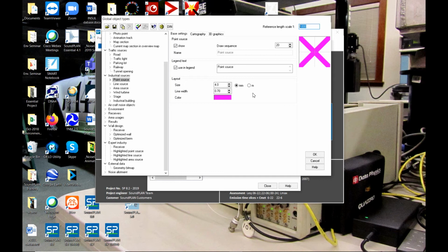What is your reference scale? So if you typically work on projects that have larger scales that are community-wide or city-wide, or if you have projects that are relatively small, you may want to change what your default scales are. And then with that, you're maybe closer to the actual end scale in terms of the definition of your line thickness or point sizes and so on. All right, so let me click OK at this point.